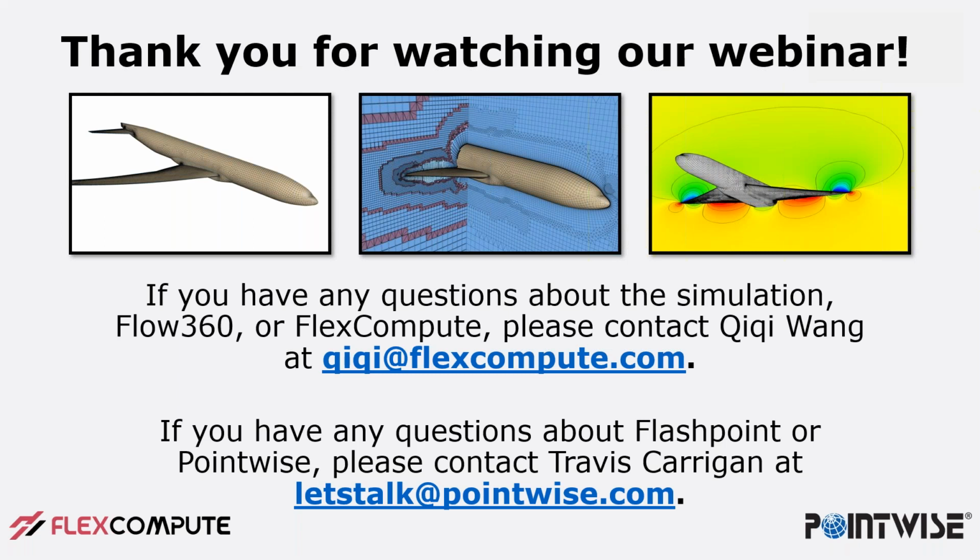Now, trailing edges are a little bit different. Trailing edges will get the aspect ratio boundary condition, and you'll see that it's the maximum aspect ratio boundary condition. The aspect ratio is also directly controllable from the global tab, and the default value is 10. The spacing is set in the spanwise direction such that the aspect ratio does not violate a value of 10. So if you wanted to control that, you could tweak the aspect ratio value. And that's a good question.